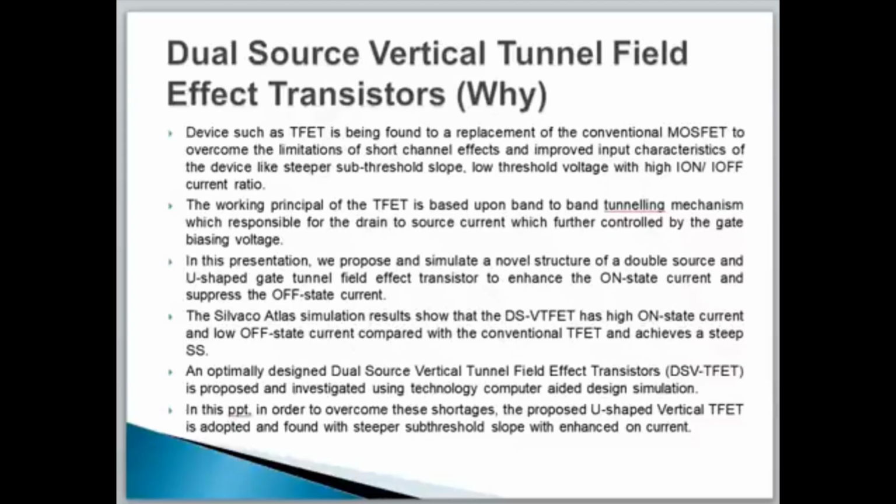There is one drawback of the conventional TFET, that is low on-state current. To increase the on-state current, we have introduced a novel structure, that is dual source vertical TFET. It will enhance the on current and increase the I-on-I-off current ratio.